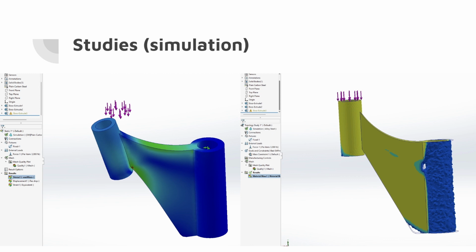Yes, there is. You can specify the parameters in here. So you could have manufacturing controls, goals and constraints. I currently have it as a mass constraint: reduce the mass by 20%, right? So to reduce most of the mass, it just strips that side. Of course, you can specify other stuff. You can give it a try at home. It'll be fun. Anyways, next.